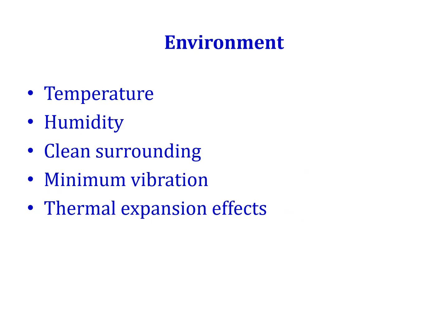Environment will also play a role in measurement, like temperature and humidity. A 1 degree temperature variation will result in 0.3 micrometer. For example, if the temperature varies by 1 degree, the length of the object will vary by 0.3 micrometer. So the temperature will influence.